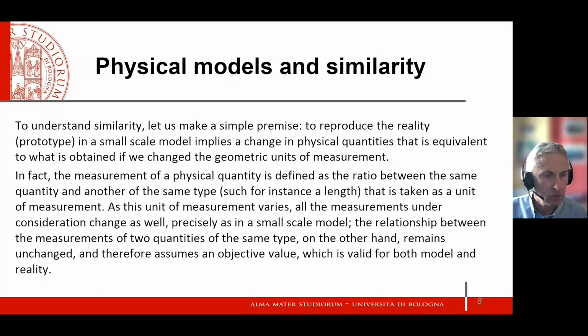So we need to understand how these physical quantities change in the small scale model, because if the velocity of the flow changes, of course, also the effect of any physical quantity that is related to geometry changes as well. Sediment transport is related to the energy of the flow and therefore to its velocity. If we change the velocity of any flow, the sediment transport may change. But there is something that helps us, a consideration that helps us a lot.